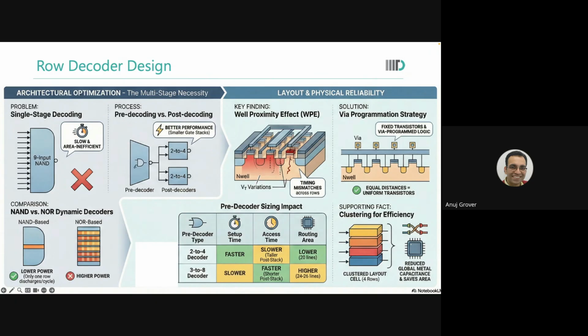To reduce gate count, because we can do much more sharing. See, unlike standard cells where sharing was prohibited, we always kept half DRC. In memories, in the memory cell itself, we saw that we want to do much more sharing. We were sharing VRs across four cells, contacts across two cells, so many things we were sharing at the boundary of the memory cell.